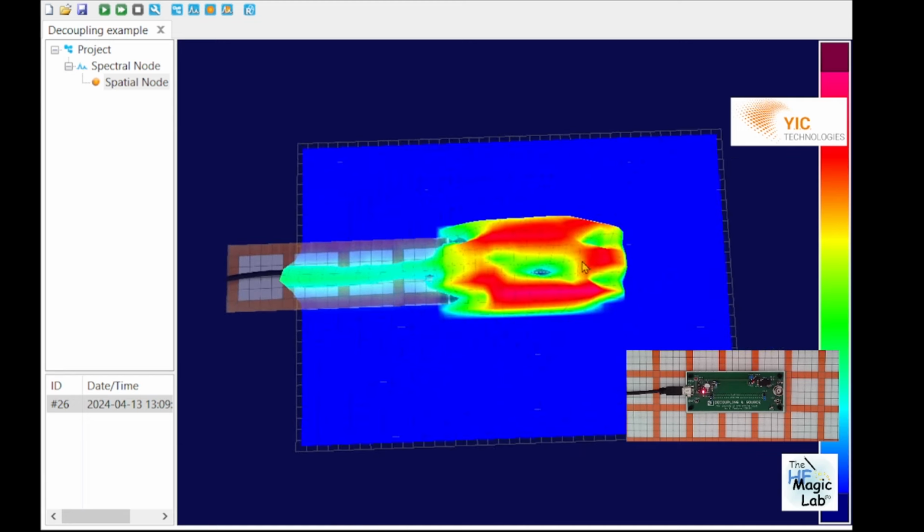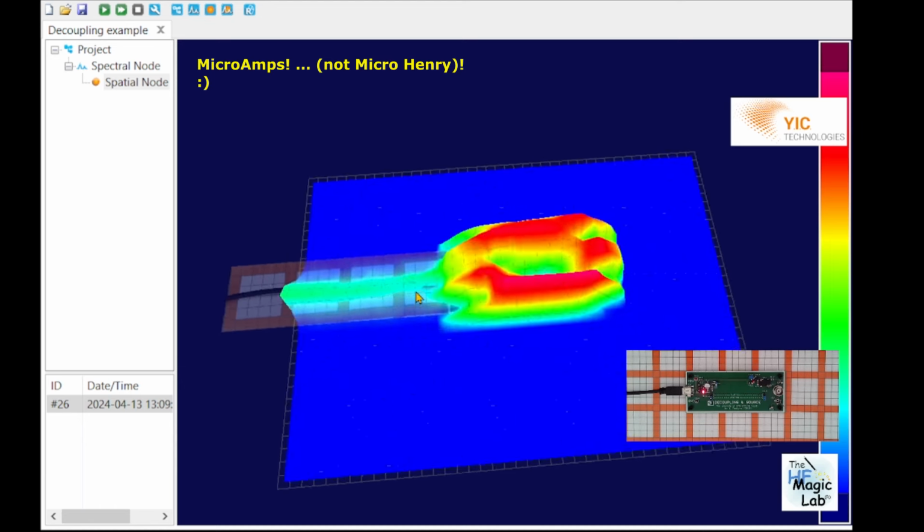The energy is not only in the loop of the PCB, the energy is able to go to the connector and additionally to go into the cable. Remember that only some tens of microhenries in your cable are able to make you fail at 3 meters in typical limits from international regulations.